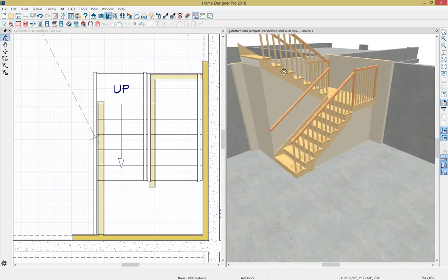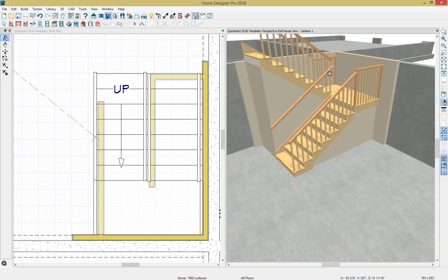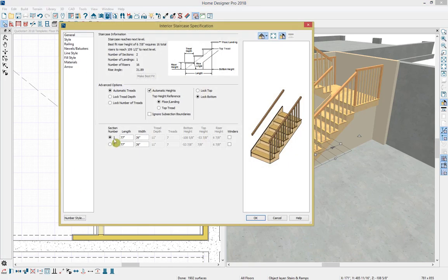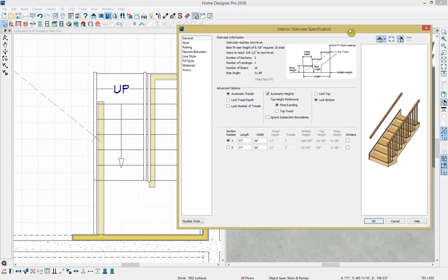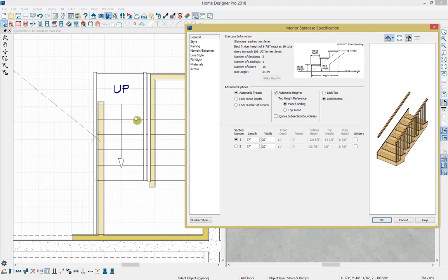So what we're going to do is open up these stairs and uncheck railing at wall, and pressing spacebar I can just select on this stair and open it, and notice I get both stair sections because we have these stairs connected with the landing and we had used that U-shaped stair tool in the beginning. We select both stair sections.